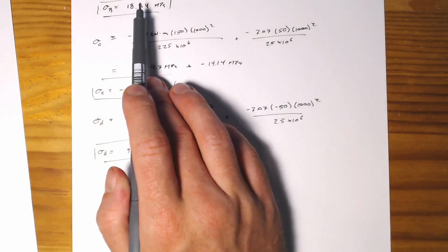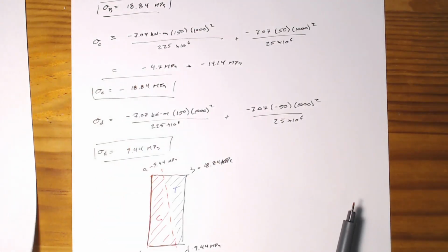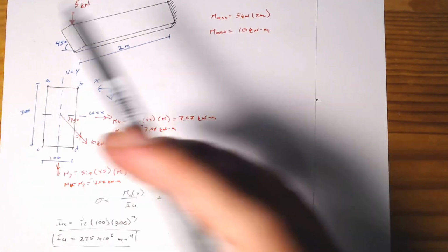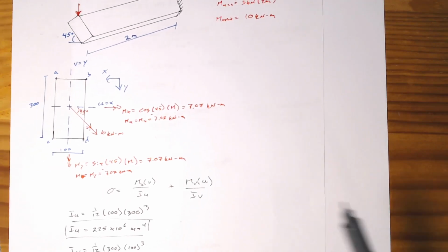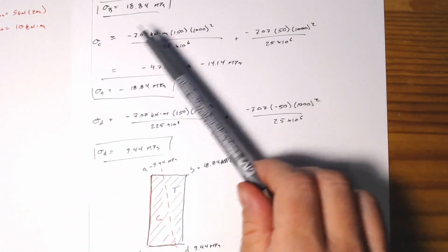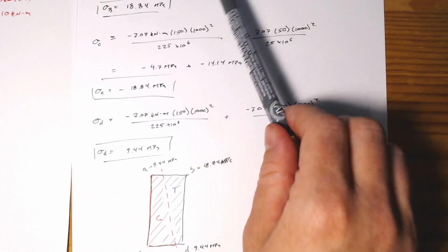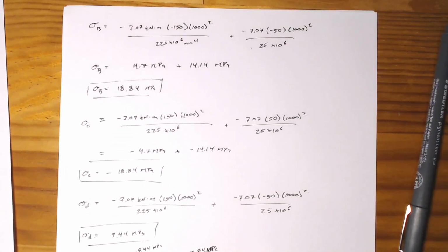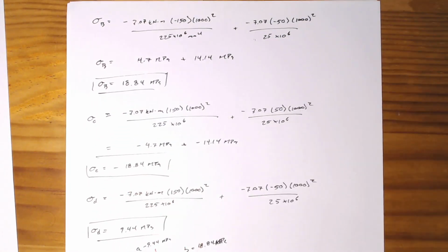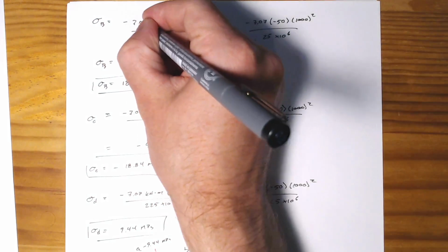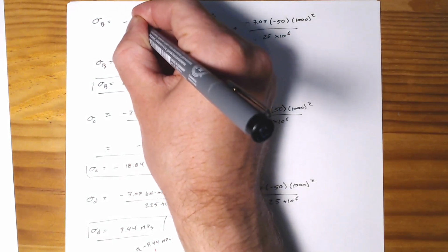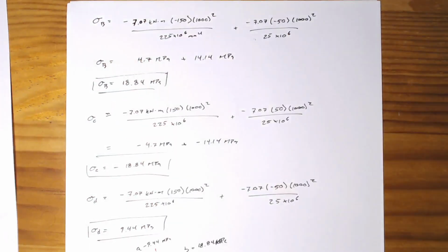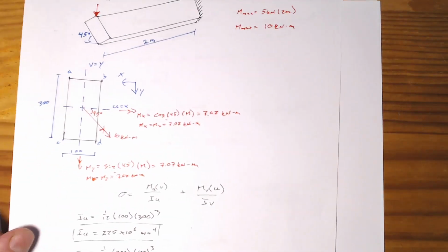As you can see, everything's kind of symmetric here. So if we know B is going to be our maximum tension, and we're finding that we're getting a compression force or it's not the maximum, well, we know we've messed up our sign notation there. As I said, it's always a little bit tricky to make sure we stay consistent with our sign conventions.